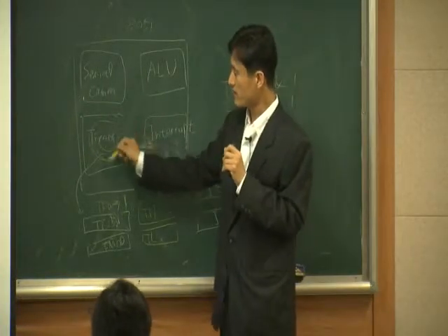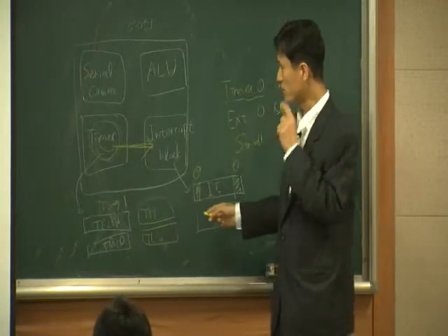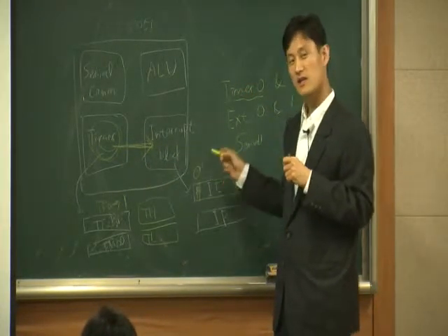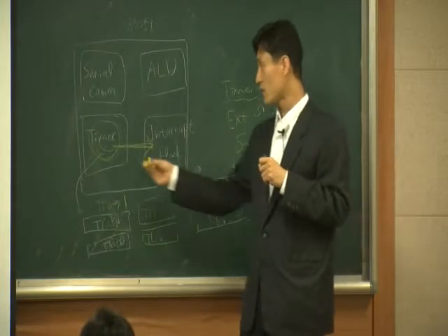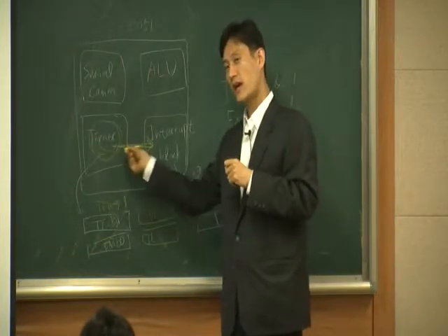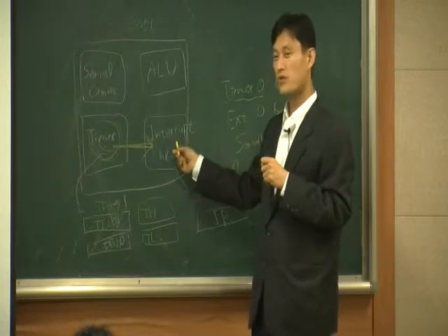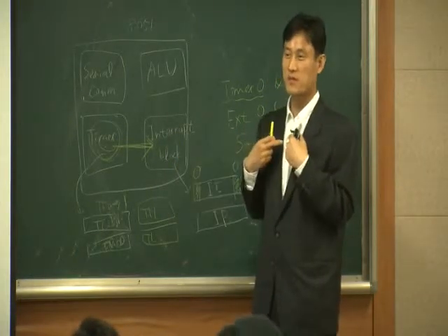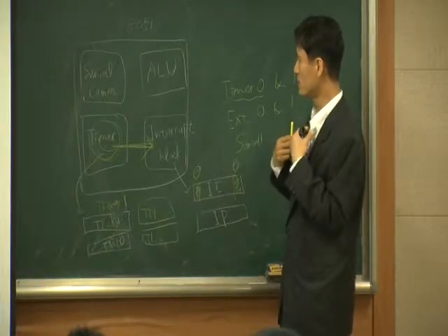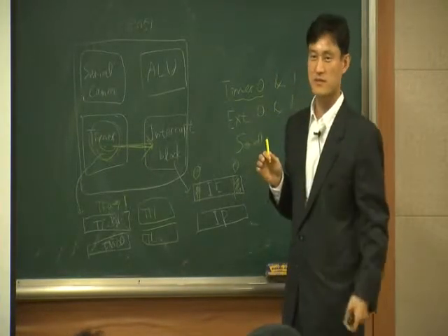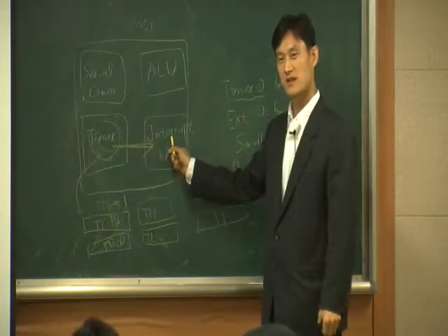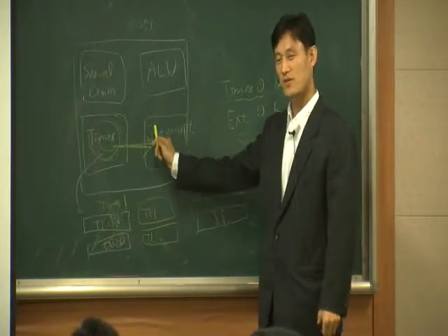You correctly configure the timer hardware, but you forgot to set this interrupt block. In that case, what happened? Actually, the interrupt event happens, but this interrupt block is not ready. Okay? So from the software point of view, the interrupt never happens. This will be ignored by this block, right? This block will ignore this.